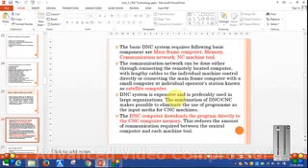The basic DNC system requires the following basic components: mainframe computer, memory, communication network, and NC machine tools. Then the DNC system is very expensive and is primarily used for large organizations where we require high production.